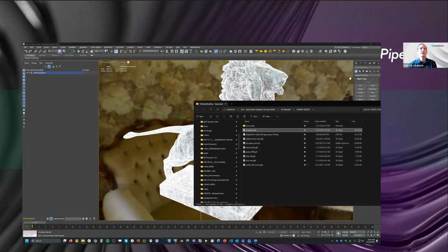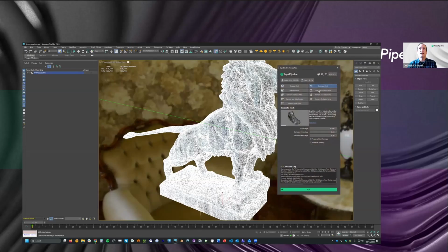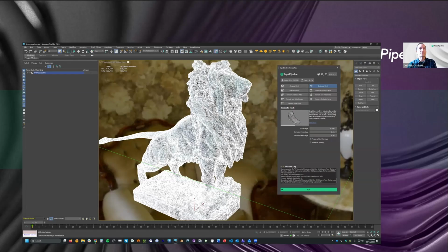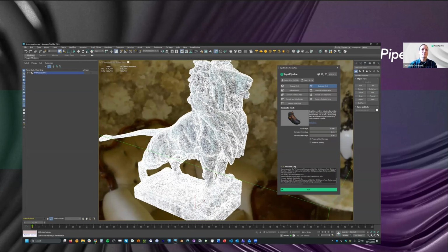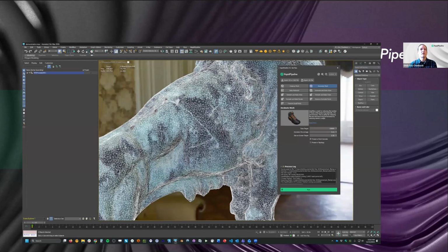So one thing you do is pull in the RapidPipeline toolset, and we can just decimate it directly. You can either decimate and bake, or you can decimate directly without baking. What I generally want to do with this kind of asset is collapse it all down to a single entity instead of 19 entities, just because it's going to weld all the seams between these different photogrammetry patches. You can see here, that's going to create problems when you try to decimate down. It might create gaps between those because the poly counts are going to be different, right?